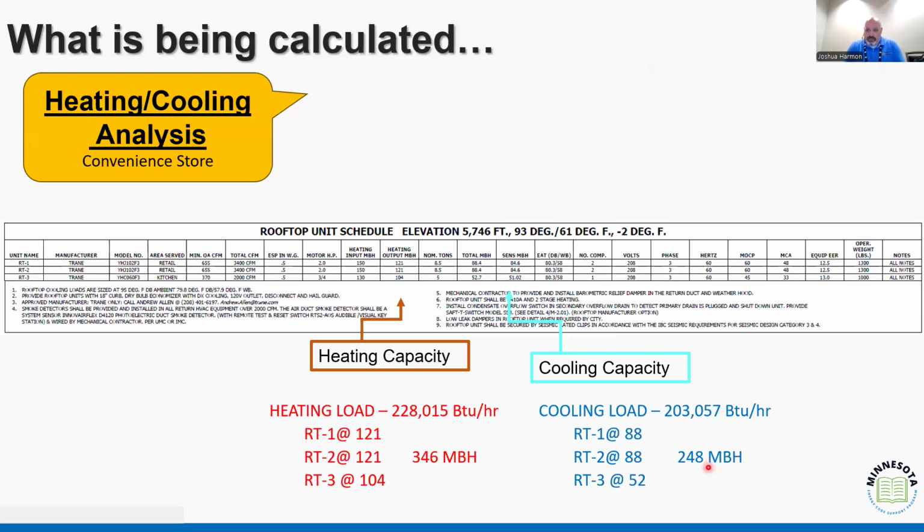Because again, we understand we might need more air because we're making a tighter building. A good standard is going to be 25 to 40% of load. A lot of times we'll talk about going a half size bigger, a full size bigger than what's the requirement, because we want to provide a little bit of cushion for that equipment. But that's the reality. Part of that is trying to understand what it is we're trying to do. We're trying to move air, or we're trying to condition space. And so a lot of times we have that conflict.